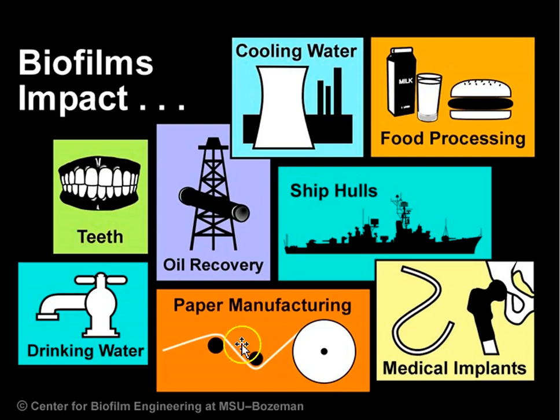Then we have drinking water. We have talked about drinking water. We've been to the drinking water plant, and one of the issues there was these barriers for microbial contamination. And in Norwegian, European regulation, you need minimum 2 absolute barriers, so that if one fails, the other one is still there, and you always have safe drinking water.